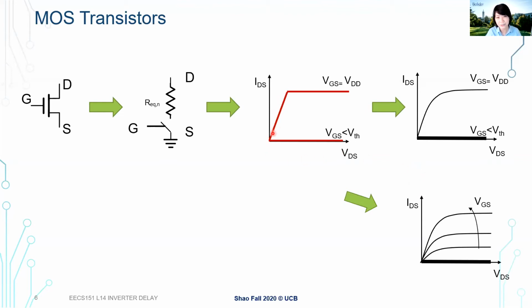Right, so that's the linear region, right? With a higher drain to source voltage, the current is increasing here. Yeah, but if we keep on increasing the positive voltage at VD, why does it not keep on becoming faster and faster and faster? Even though the channel is limited. Right, I got your question. So you're basically asking about this saturation region, right?